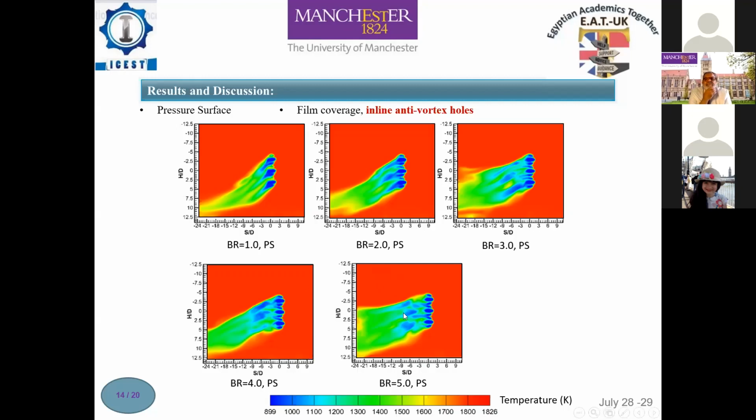In this case, the exit of the side holes are very close to the main hole, so the coolant jet interactions from the two side holes are very prominent. The coolants from the two side holes interact between the main hole and generate another jet streak similar to the main coolant jet. Further downstream of the film holes, the jet streak of the side holes mixes with that from the main hole and thus creates a thicker coolant streaks footprint than that from the other cases. The footprint of the coolant can be recognized in the near hole region.